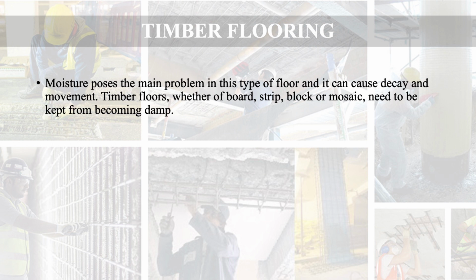Here the biggest problem is moisture. Moisture poses the main problem in this type of floor and it can cause decay and movement of the floor. Timber floors, whether of board, strip, block or mosaic, need to be kept from becoming damp. Dampness should not be allowed.